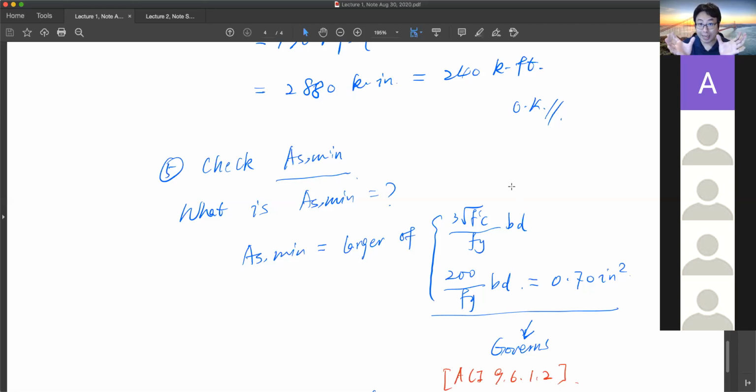So there's a self-weight of the beam, first of all. So when you're trying to lift the concrete beam out, the beam actually bends due to the self-weight. However, the tensile strength of concrete is very low, so it can easily break down. There was an instance in aircraft hangar structures back then in the military base where they forgot to put enough reinforcement in it. They just used some mesh wire. They did a calculation and supposed that the self-weight would not crack the concrete, but it ended up cracking the beam.